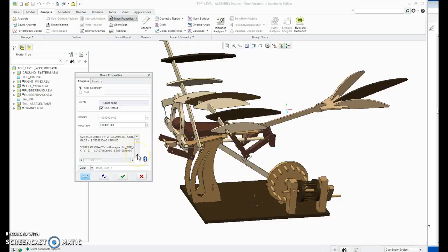Now, if you actually sneak peek a little bit down, it tells you exactly where your center of gravity is, and it actually tells you your inertia tensor. And if you actually remember from physics, inertia is the resistance to change in motion. So how hard, and tensor has to refer to three-dimensional space, how hard this device is to turn, which if you're trying to fly, pretty important as far as predicting control algorithms is knowing that information. And so there's a bunch of things here that you might not ever use, but it's definitely here, and you can see that.